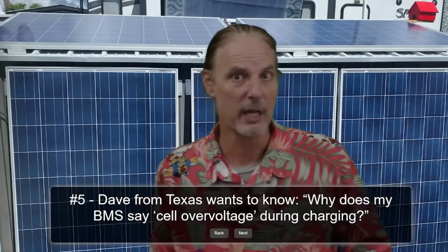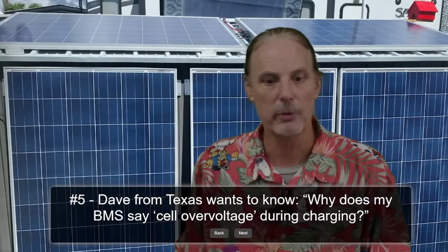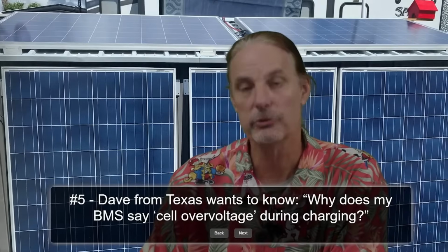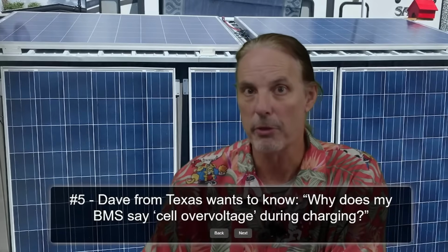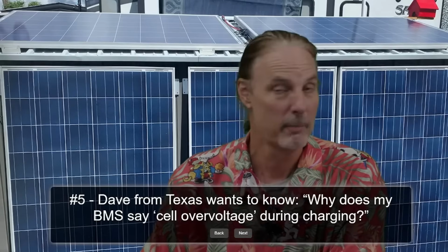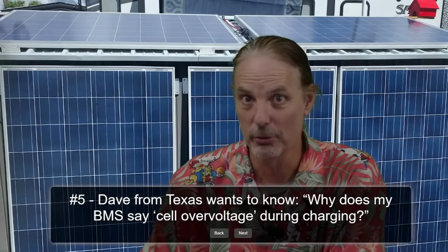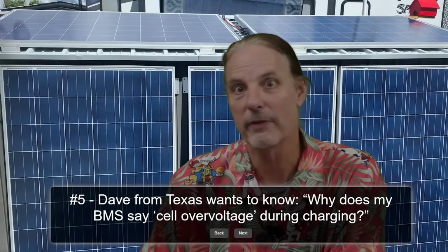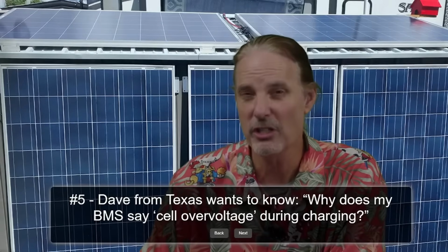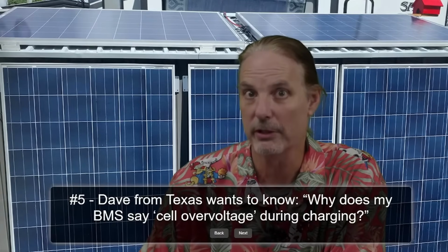Because at this point, the lowest cell in that pack that we had over there on the demo is 3.3 volts. And that means that that whole battery is going to perform at 3.3 volts capacity, not at the 3.66 volts, because the other battery cell will shut the pack down when it gets too low, and it won't be able to use all the energy stored in all the other cells, because the one cell, just as charging stops when you get too high, discharge stops when one cell gets too low.